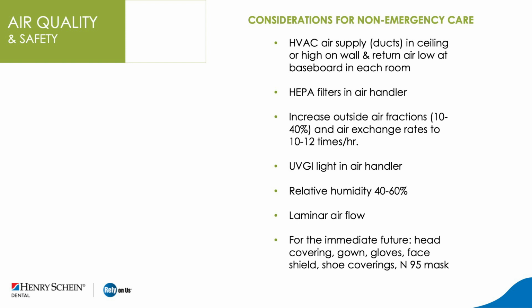Consider using UV GI light in the air handler. But as I said, this is not usual and customary in commercial systems, and it really is not efficient in the larger commercial systems. And if you're using HEPA filters, it may be somewhat redundant.